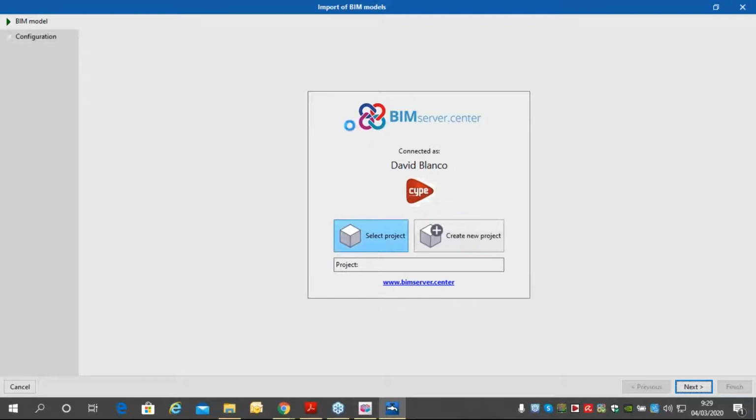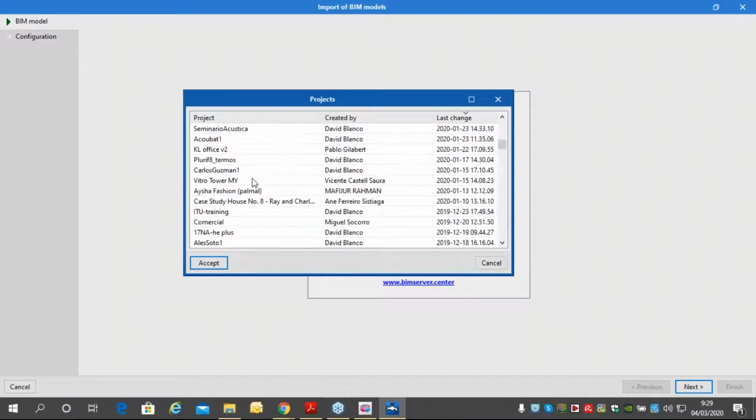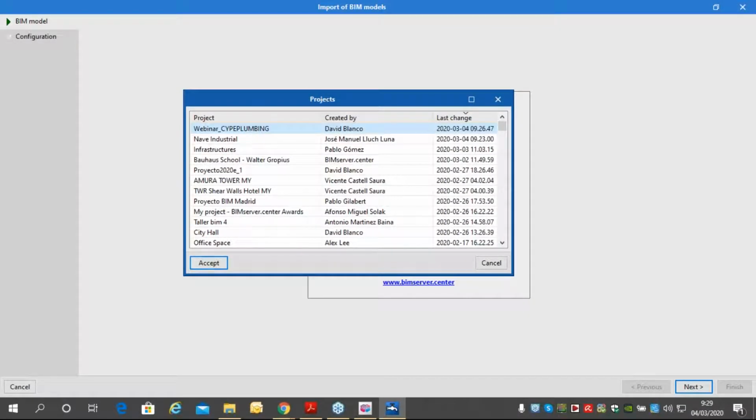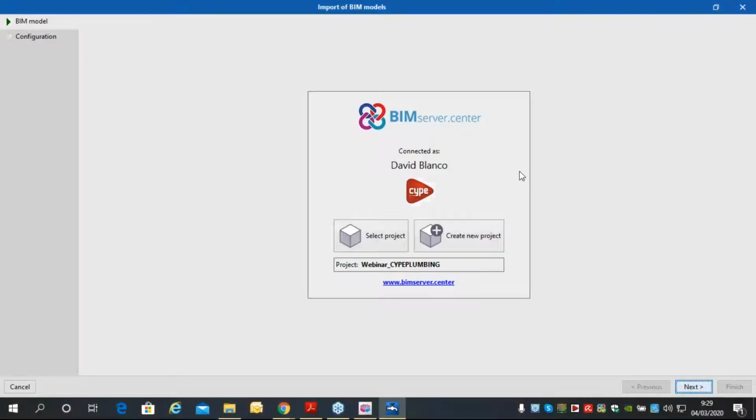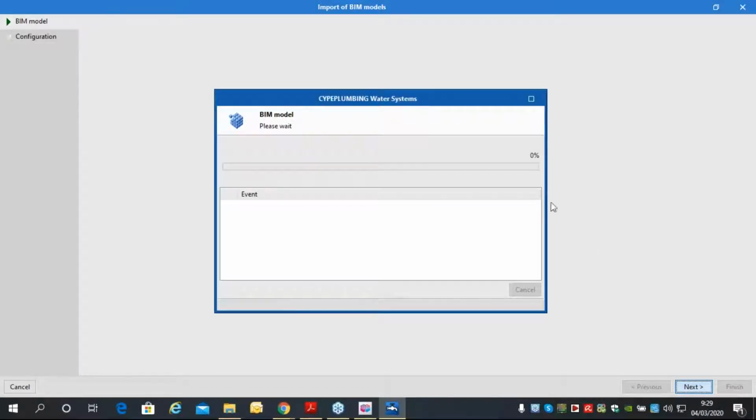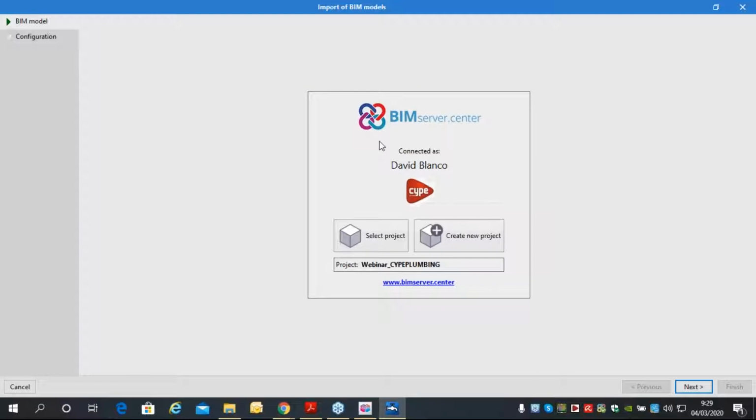So we are going to select the project. I'm going to search in my list, project webinar site plumbing, accept, and click on next. This wizard is going to guide us in the creation of the project. We are going to create a new water system installation, starting from this BIM model I have generated by IFC Builder.